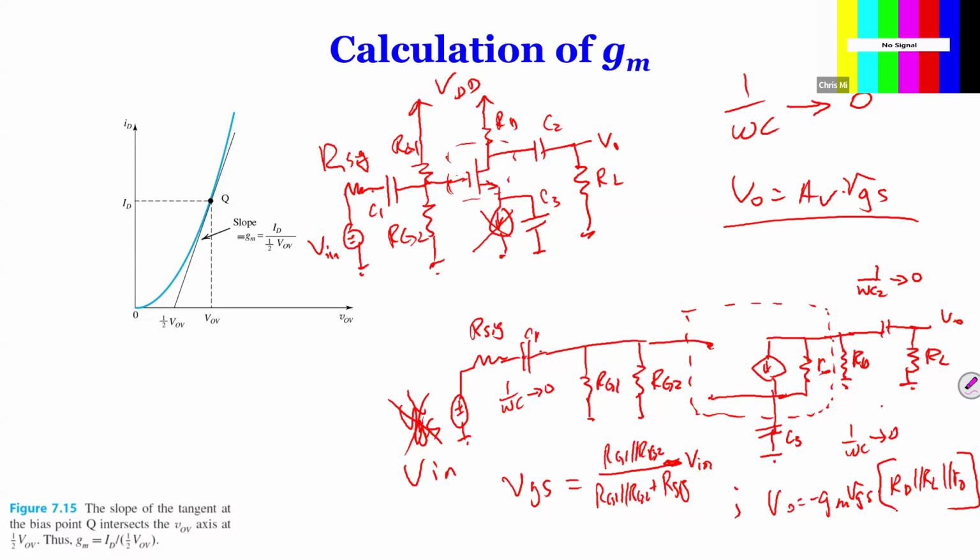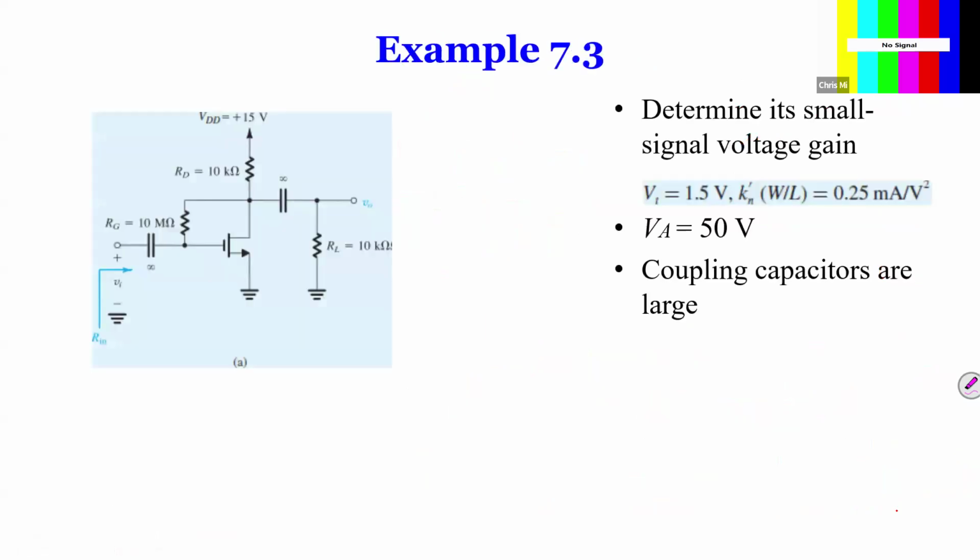So far we have this pi model. Sometimes we call it the hybrid pi model. It's like a pi, right? This branch is especially for BJT. It does look like a pi, or maybe the reverse pi. But we're going to develop another model, called the T model. What they're doing is to make it mathematically easier.